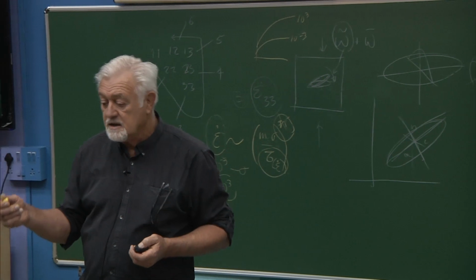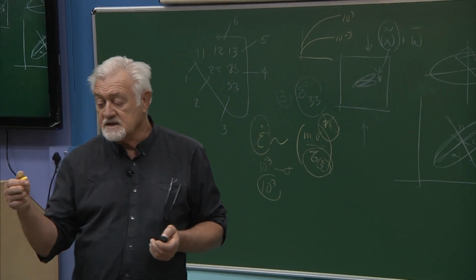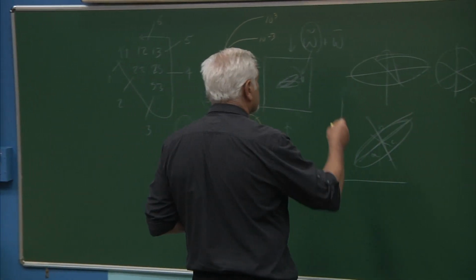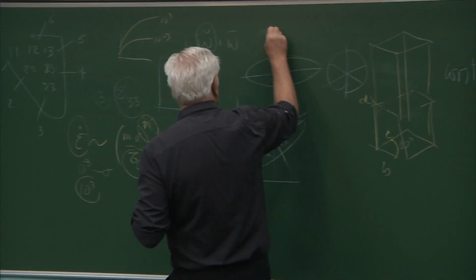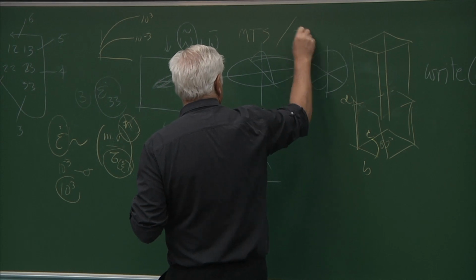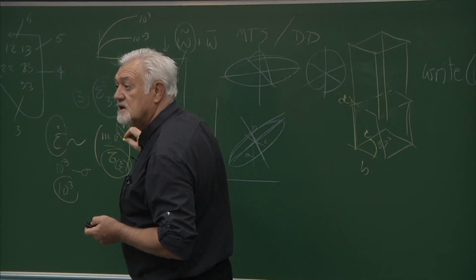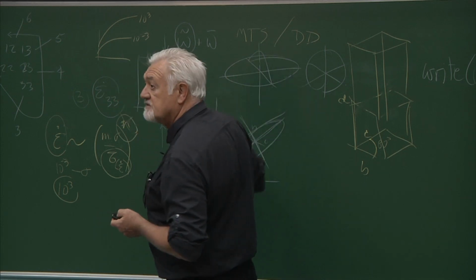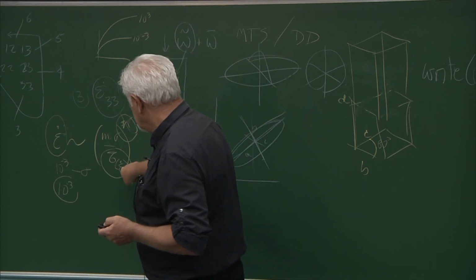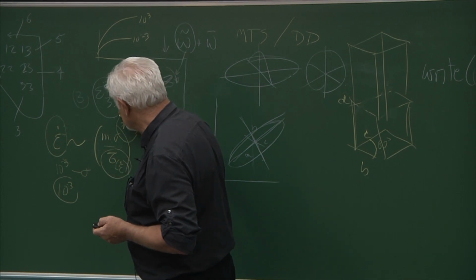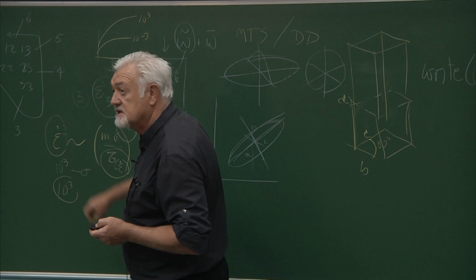And yeah, in the examples in the code, you will see the MTS model and also the dislocation density model. Those models have the rate sensitivity introduced in the taus, and so they eliminate the rate sensitivity coming from this cell.